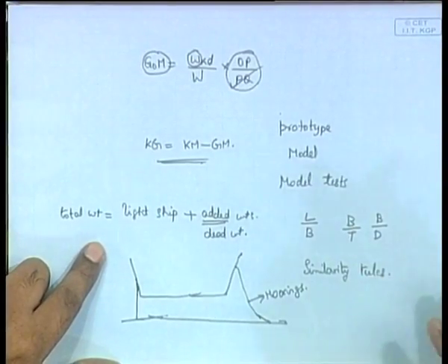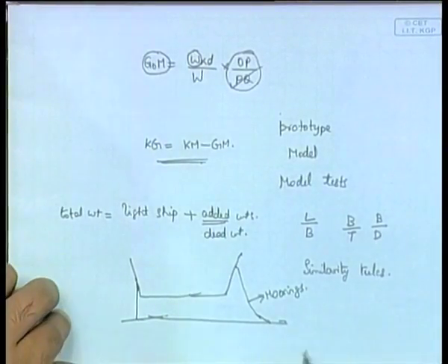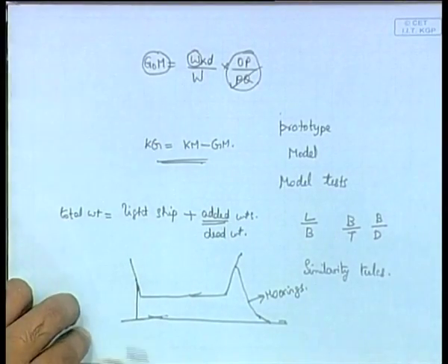The other condition for that is you do not have moorings in this; the ship is in a free condition, nothing else. It is very important when you are doing this experiment that you should not have waves, because if you have waves, your results will incline much more than what this predicts. So, it should be absolutely calm water like you have in your towing tank, with nothing moving there, no ship and no body moving.